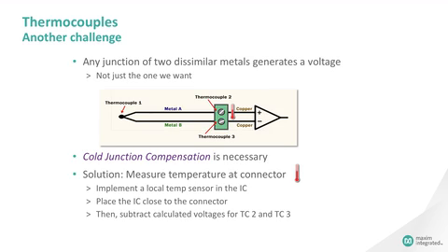Of course, implementing an ice bath is both expensive and impractical in most situations. Since low-cost silicon temperature sensors are readily available, it is much simpler to measure the temperature at the connector, then calculate the voltages generated by the unwanted thermocouples.